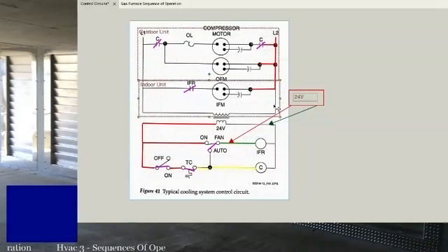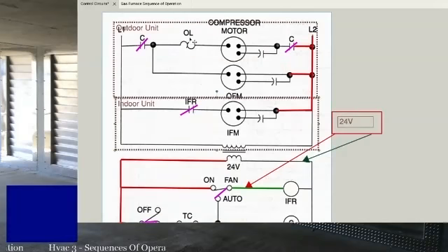But if you don't know your sequence or you don't look at your wiring diagram, you could be missing an important component that would tell you what's going wrong, right? If you don't know about that compressor overload that's inside of the compressor, you might think the compressor's bad when you electrically test it, when if it's got an internal overload, you might be able to wait 20 minutes and that overload closes and then you can get it to run. So you need to think about all the components that are in the circuit, what the sequence is, what should be running, what shouldn't, eliminate as much as you can, and then check all the components that are left on your control circuit for the issues that it could be. And if you're looking at your ladder diagram, you should be able to narrow it down to all the components that might have an issue.